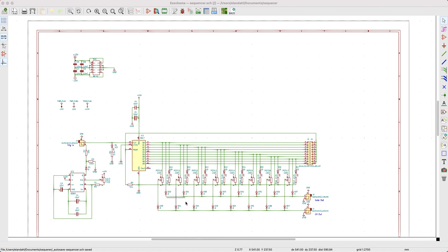So again, each of those potentiometers fires in sequence. Each of them is attached to a different output of this decade counter. Now there are two more, actually in fact three more connections on each wire. One of them is simply an LED, which we used for visualization, so you could tell when it was firing and that everything was working. That's just an LED in series with a 2.2K resistor as a current limit.